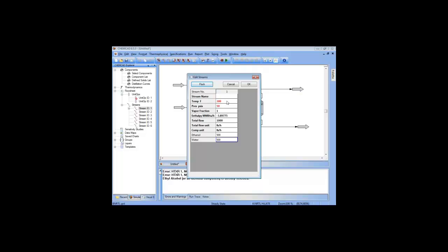If you wanted to do some different calculations with this, you can. You don't have to specify a temperature necessarily. You can specify a vapor fraction. This gives you a saturated vapor at that temperature. That corresponds to the dew point, the point at which just a little bit cooler, we will start dropping out and condensing things.